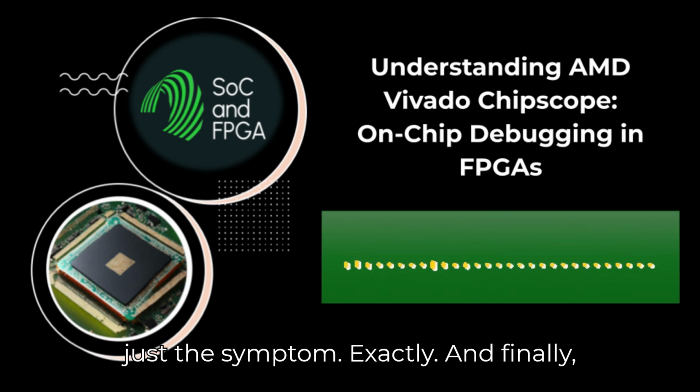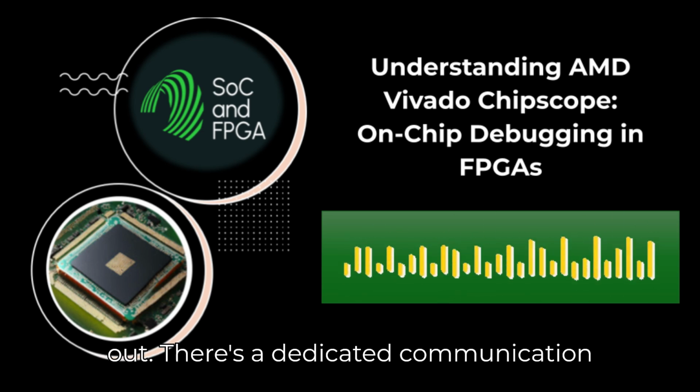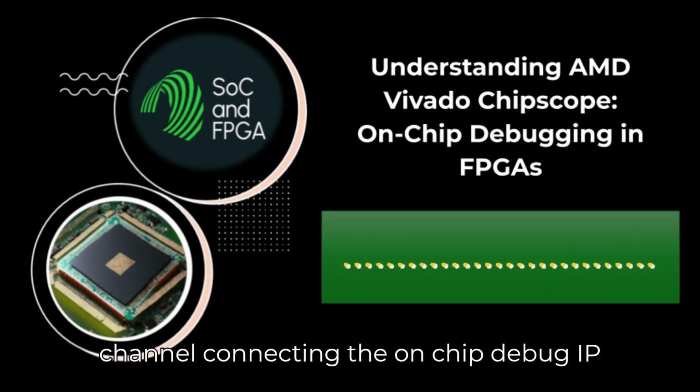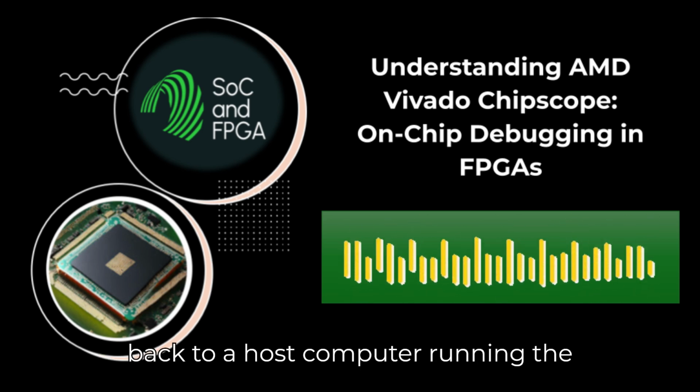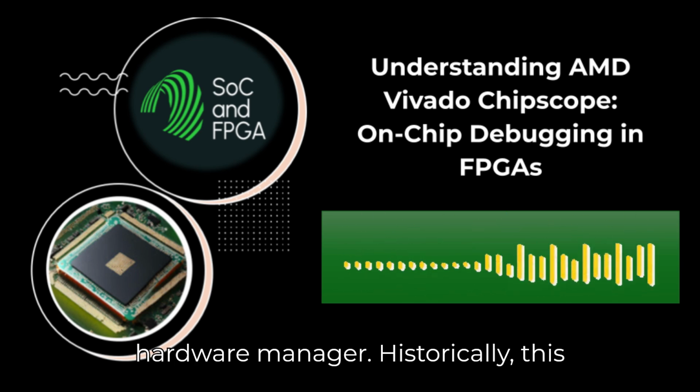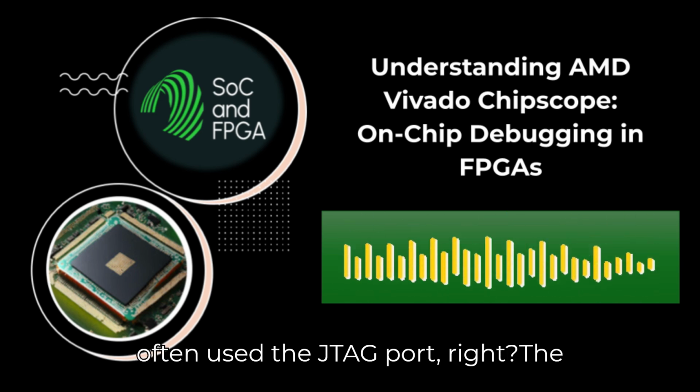Exactly. And finally, when data is captured, you need to get it out. There's a dedicated communication channel connecting the on-chip debug IP back to a host computer running the analysis software, like the AMD Vivado hardware manager. Historically, this often used the JTAG port. Right, the standard debug port.